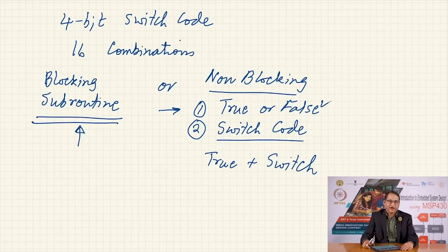So, this is not a very advisable method, and you would notice that when you insert your ATM card, it asks you to enter your PIN number. If you do not enter your PIN number for a specified period of time, the ATM machine returns your card and says timeout. This is to indicate that the subroutine for the keypad on the ATM machine was written in the non-blocking fashion.